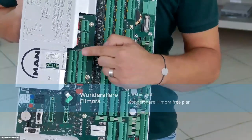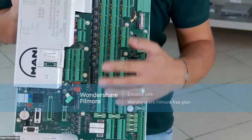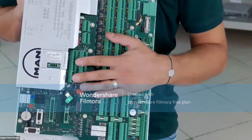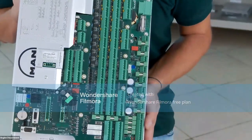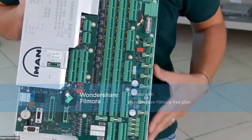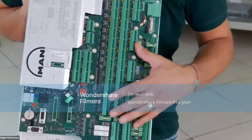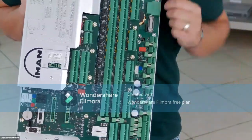But the application CCU3 from other vessel is different than on my vessel. Maybe it was CCU3 on 9-cylinder, and now I want to install a CCU3 on 6-cylinder engine. So the application is different, okay? But because the name of the application is CCU3, it will not be any conflict, and the engine, it will operate, this MPC, it will operate with a CCU3 application from another engine.